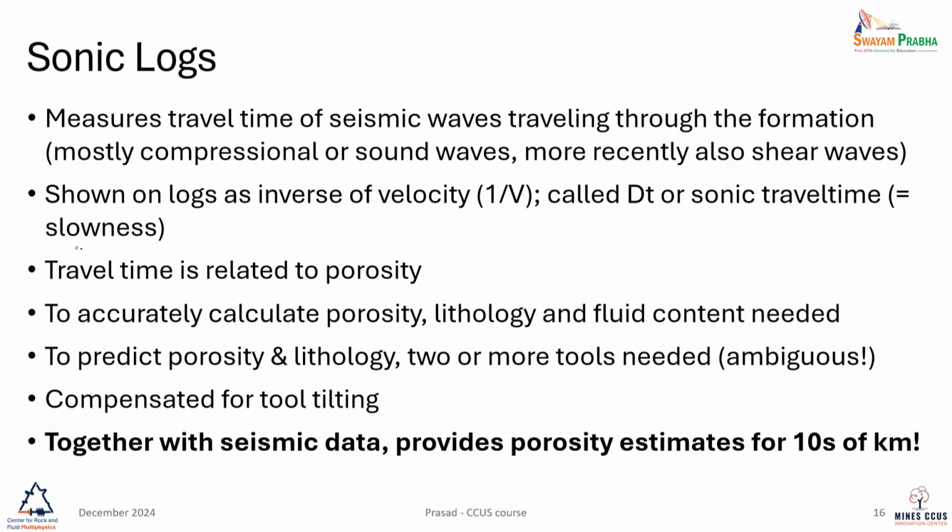That is called slowness. Now, travel time, as it turns out, relates to porosity, which is a good thing because we can use that, calibrate it, and use that information to develop porosity maps. To do that, we need lithology and fluid content, and we need a good model.